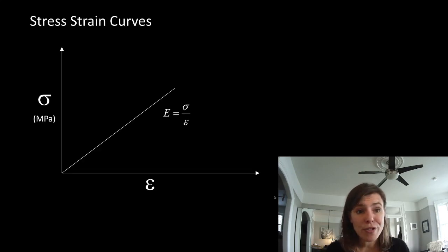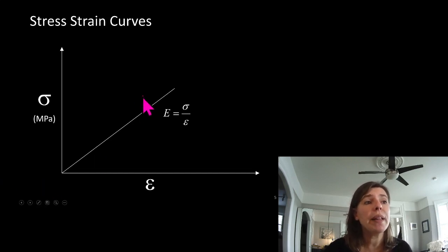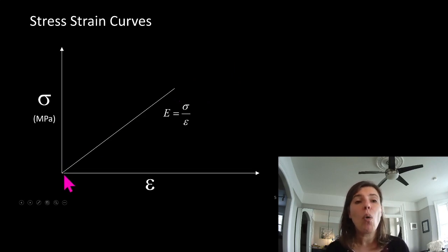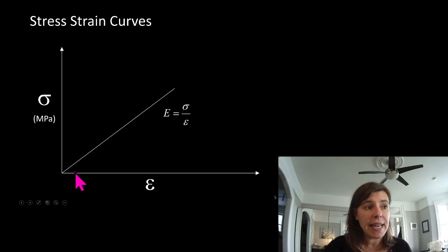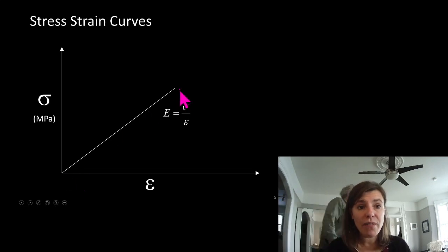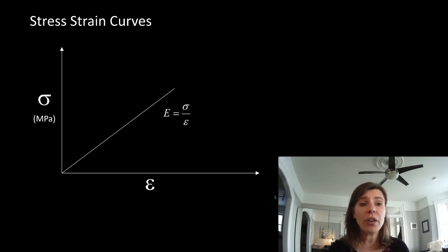We talked about stress-strain curves last week, and what we really care about is this zone here, which is the slope where it's in the elastic zone, or if we unloaded it, it would go back to its original shape. Many materials, when they hit the end of this elastic zone, fail. That is it, that's the end of it, because they are brittle materials. Wood is a brittle material. Concrete on its own is a brittle material. Steel is not a brittle material, it is a ductile material.